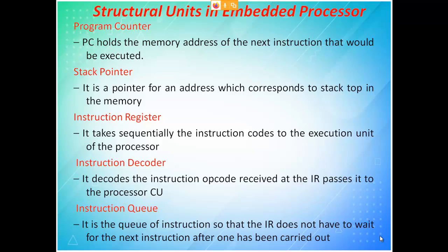If it is a queue of instructions, the instruction register does not have to wait for the next instruction after one has been carried out. So the instruction register will send to this instruction queue, and this queue will send them one by one.